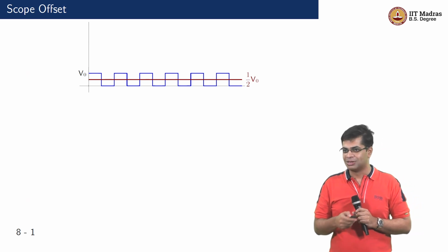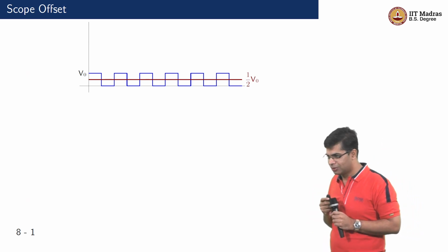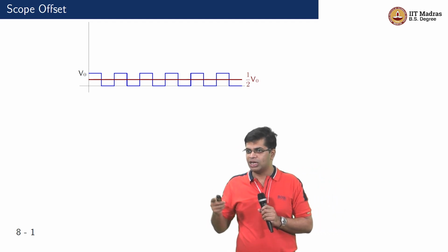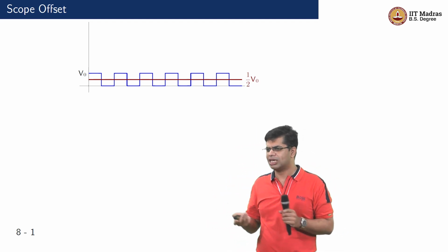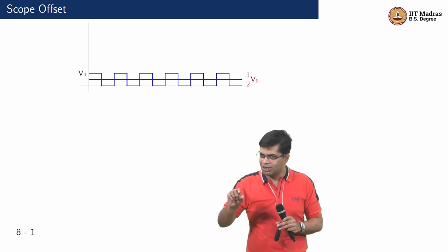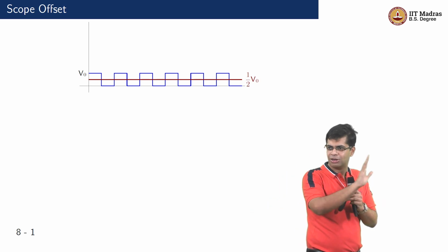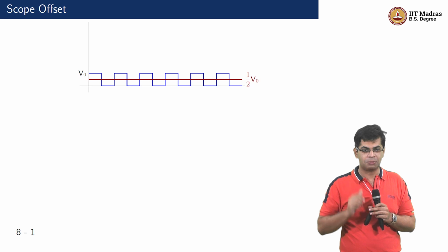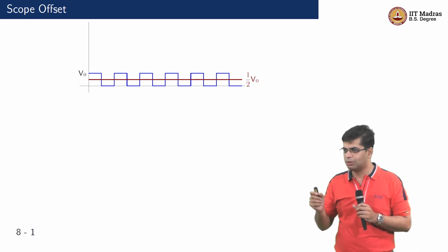Okay. Next. So how do you implement the offset? Remember, there are constraints. If I had a D2A converter, if I had lots of D2A converters, I can use a D2A converter, set, depending on where I have the slider, a digital value and then use that. I don't have so many D2A converters, but I have these pulse width modulator modules, PWM modules.